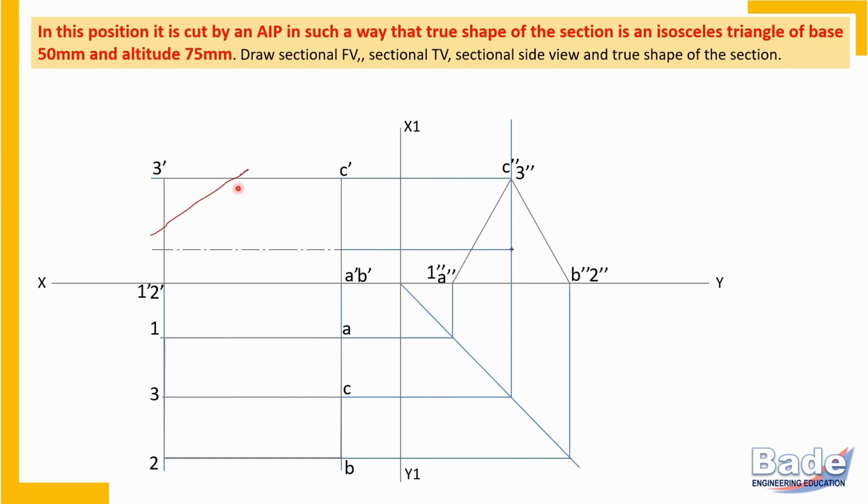then you will get one corner for the section here, that is PC, and the cutting plane is intersecting the triangular surface which is numbered. So here we should label these points as S and T. So 2 points here on the numbered surface and 1 point on edge C3, that is PC. So if the cutting plane is in this orientation and in this manner, we'll get a triangle.